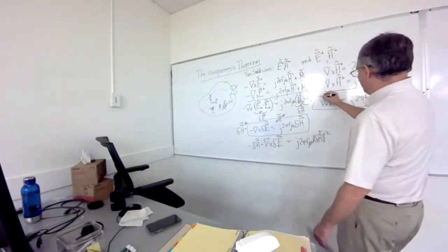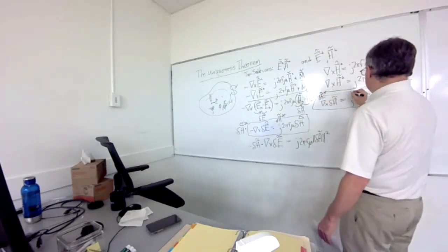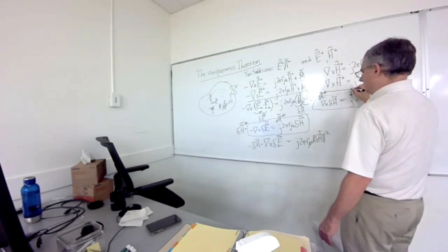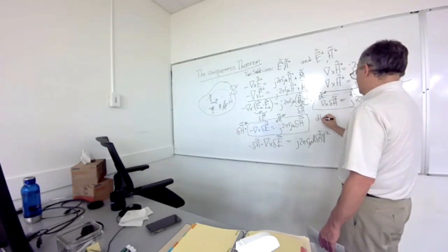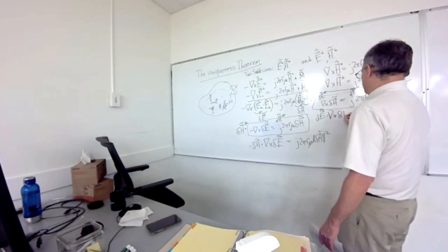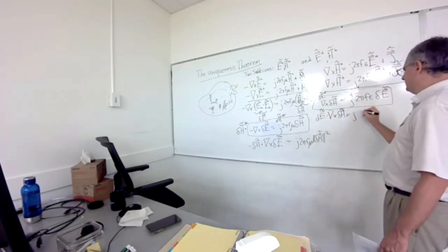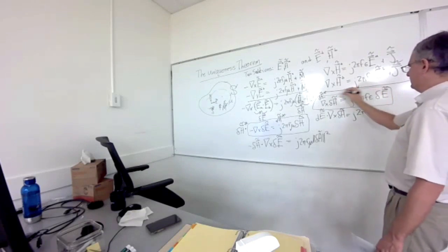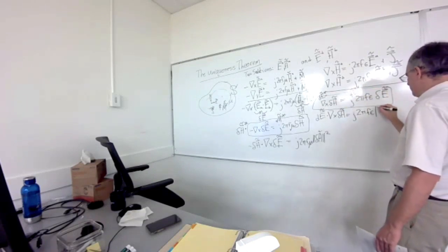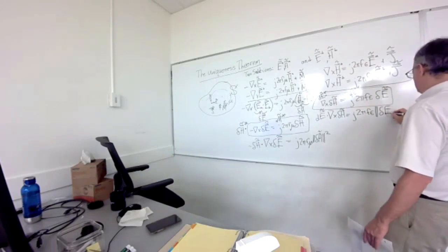Likewise, I can do the same thing. If I dot delta E complex conjugate into both sides of this one, I get delta E phasor vector dotted into this phasor vector curl of delta H is equal to j 2 pi f epsilon. delta E dotted into delta E gives you the magnitude squared of my delta E vector.